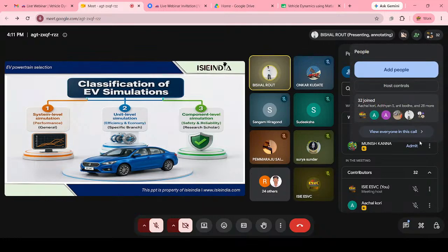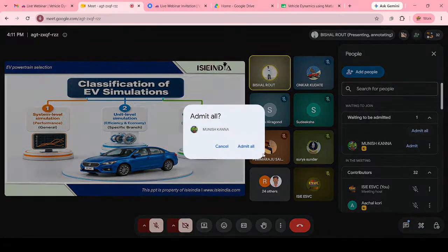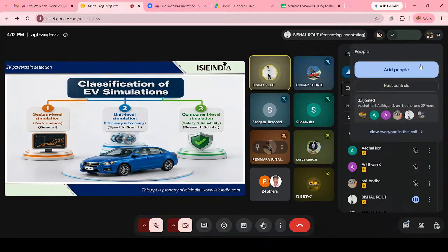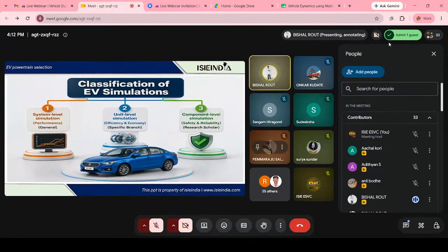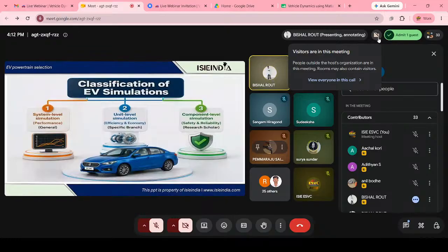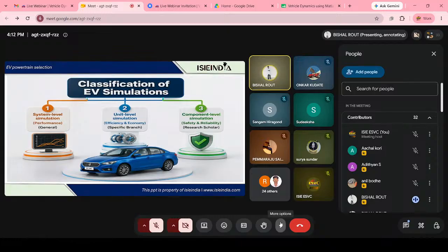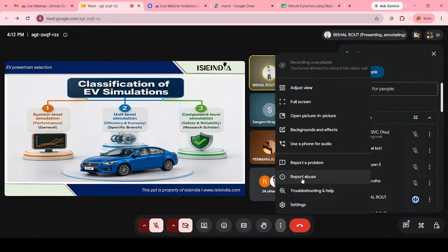What gradability can it achieve? What kind of energy consumption is happening? What must be the driving range? How does the battery SOC vary with respect to speed? We can also understand motor operating regions, regenerative braking energies, even battery power demands.